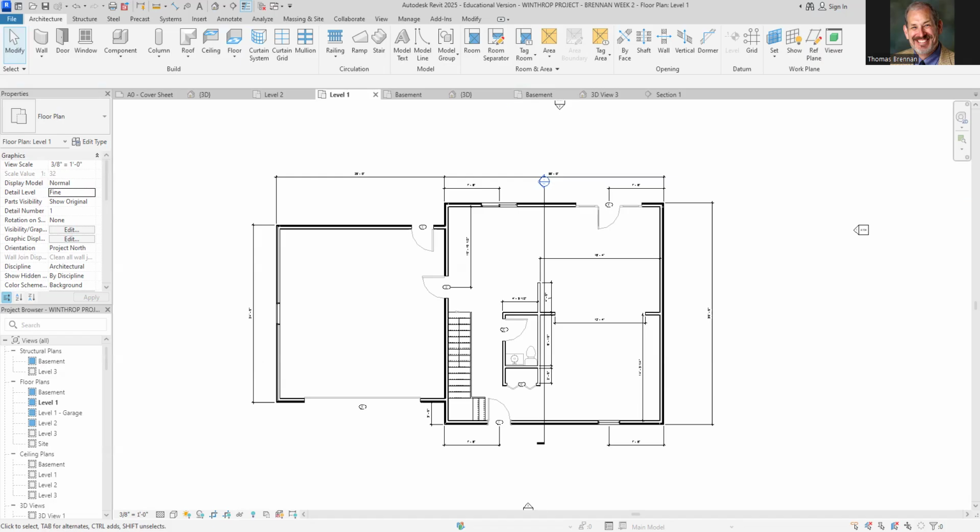So click on either one of those. And when you click on the line that makes up the section marker there, Audrey, click right on the line and then unhide in view, or unhide and choose category. Okay, and then go down to the bottom, click the light bulb now. You don't want to delete it. All right, there. Now double click at the top on that symbol that looks like a circle with a triangle. There you go. You got it. Nicely done, Audrey. Looks good.